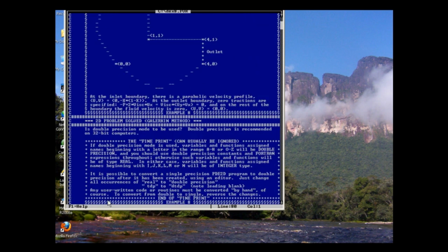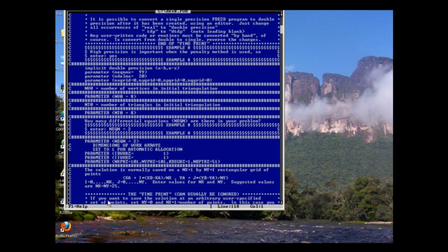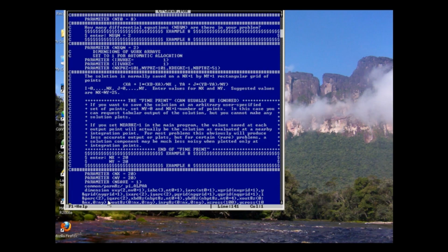Typically, the user will create a program using either the GUI or interactive driver interface, and then for a long time make changes directly to the Fortran. You don't need to rerun the interactive driver or GUI unless you make major changes, such as going from a 2D to a 3D model. And again, you don't need to be a Fortran programmer to make these changes.